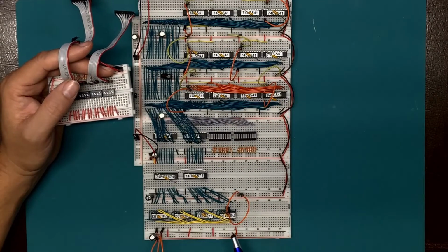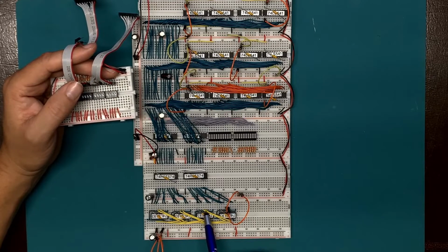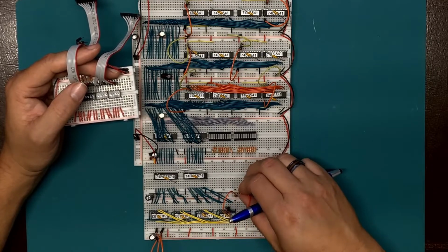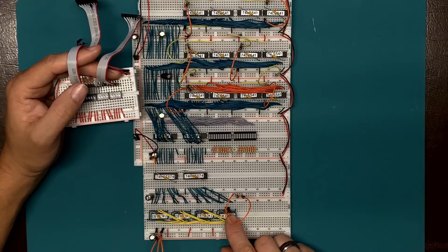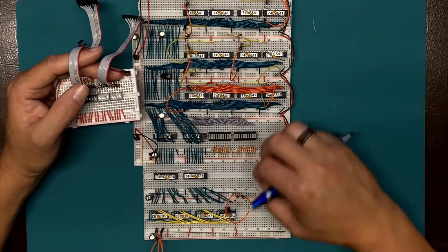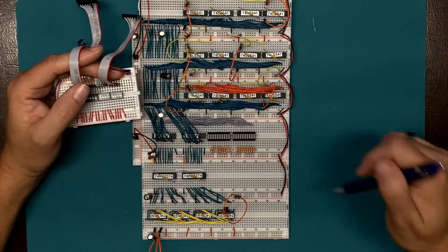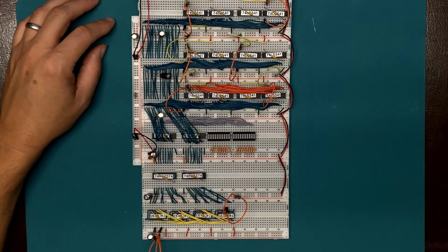Coming back to the overhead, normally these 2 pins are high, meaning that the inputs here on count up and count down are normally high, and then they go low right before they're supposed to go back up. So what I'm going to do is move these 2 control lines to high so that it mimics on the least significant nibble exactly what's going to be seen on the other nibbles. And that's how I will work on constructing the control logic, is to mimic that same pattern all the way across. I also added a decoupling capacitor here for the power rail that I added.